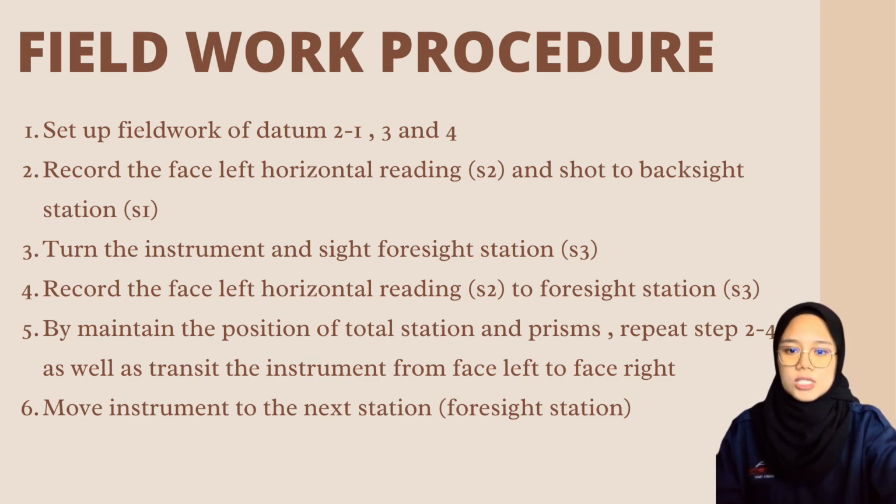To maintain the position of the total station and prisms, repeat steps 2 to 4 as well as transit the instrument from face left to face right. And last, move the instrument to the next station.